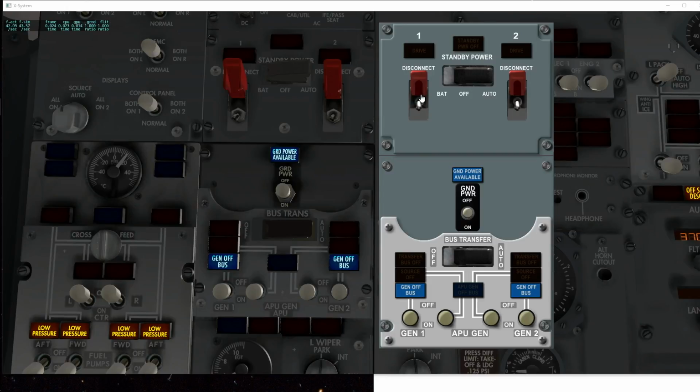I'll flip the switch on the disconnect, and you can see the drive light comes on to tell me that it's been disconnected. Also, when the drive overheats, there are other times that this drive light will come on when it's still connected, and generally it will auto disconnect if it has a problem. But once, like I said, you can flip the guard back down, but that thing is disconnected and it's not being reconnected for the rest of the flight.